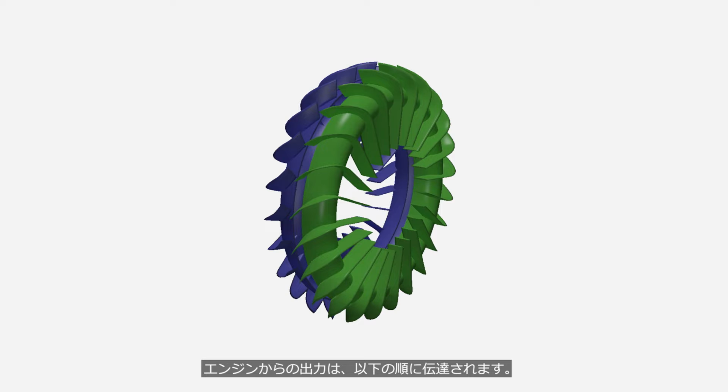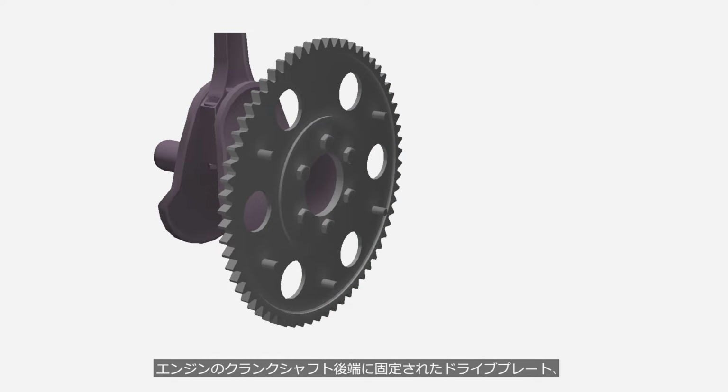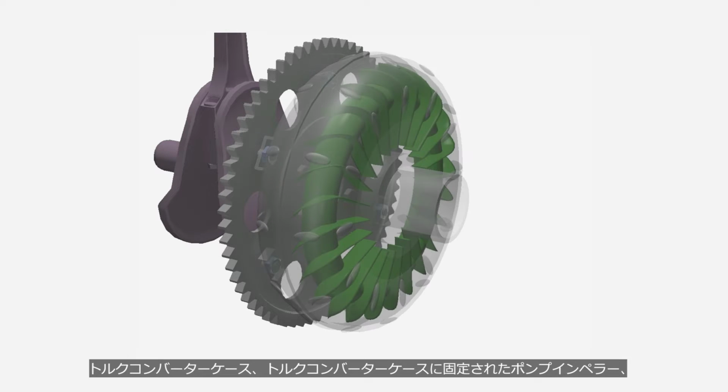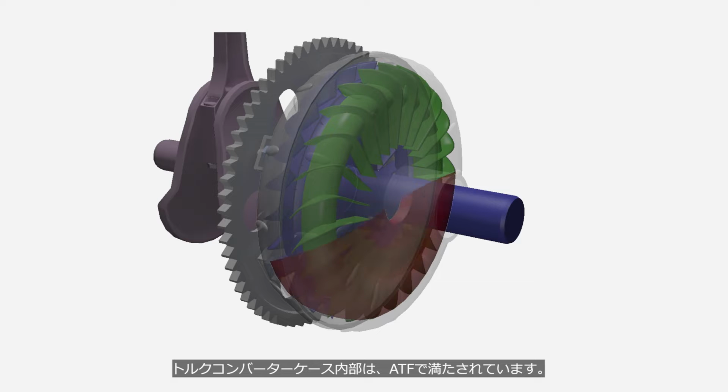The power is transmitted in the following order: from the engine, to a drive plate fixed to the rear end of the crankshaft, to the torque converter case, to a pump impeller fixed to the torque converter case, and finally to the turbine runner that can rotate freely, which then outputs power to the transmission side. The inside of the torque converter case is filled with ATF.